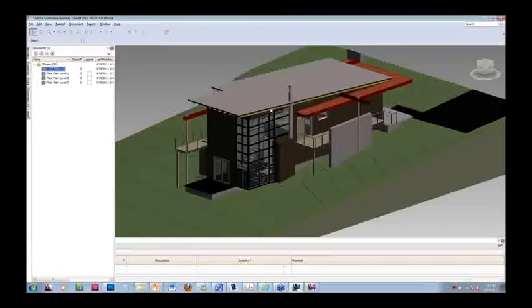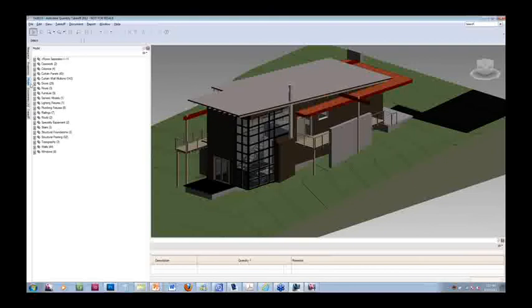So right now, this model, if I go to model, you'll see that every little thing from Revit, as long as it was created under the right category, is going to be listed here. It means that right now there's no mapping assigned, so pretty much it's just taking off every single entity from the Revit model, or from any model that can be exported into a DWF. So once you have this, it's just a matter of mapping it from here, or there's another way that is pretty quick and simple.